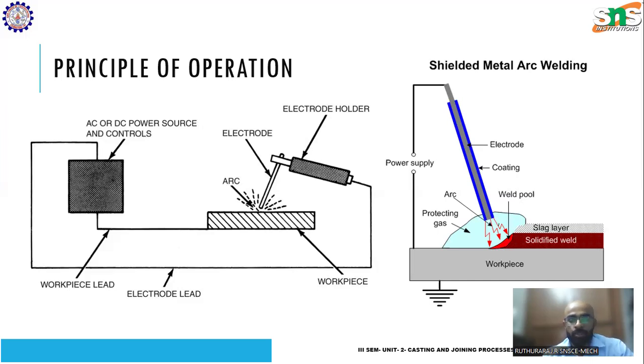If there are some impurities in water, what happens? It suddenly becomes a conductor because free electrons are available. Similarly, in the arc welding process, the oxygen, nitrogen, etc. are ionized. O2 becomes O, nascent oxygen, and nitrogen becomes nascent nitrogen. So it becomes an ionized state. Free electrons are available, so electrons can flow from the electrode to the workpiece.